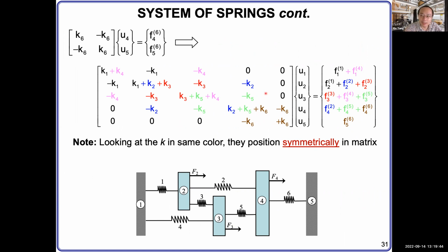So now, up to now, we have a global matrix generated, and the displacement vector remains here, and we have a global force vector generated. So here, those are the forces generated and applied by the spring on the node, collectively on each node.